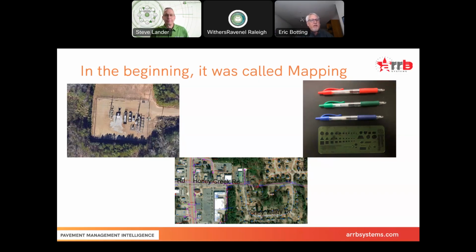So the top left of your screen, you'll see an aerial photograph. Actually, it was a satellite image now, but back in the day, when we were doing mapping and computers were just not involved, our company worked with an aerial photograph company. They would get all these quadrangle maps and come up with a flight plan and fly back and forth, and then take those negatives, and we had a huge camera system. We had a guy that would do all the measurements so that we knew how to set the camera and it would be the perfect scale for the data collection.